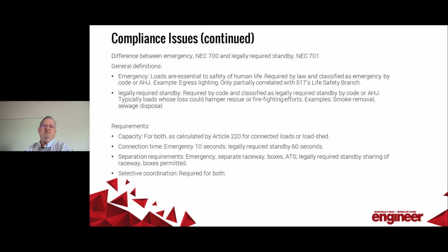Okay, what's the difference between emergency loads and legally required standby? Those are defined in NEC 700 and NEC 701. 700 loads require standby service either by law, codes, or the declaration of an AHJ, and they're specifically described as emergency. They're essential to life safety.